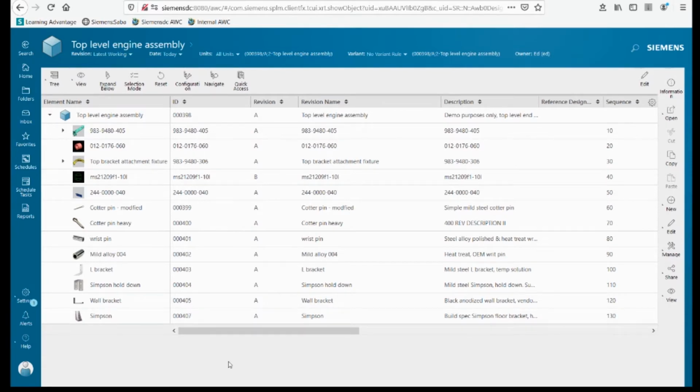It's the result of combining many possible bill of materials into one product structure. Hence, we refer to it as 150% BOM. And it contains more parts and subassemblies than needed. But as a result, you do not need to maintain separate bill of material for every variation possible.